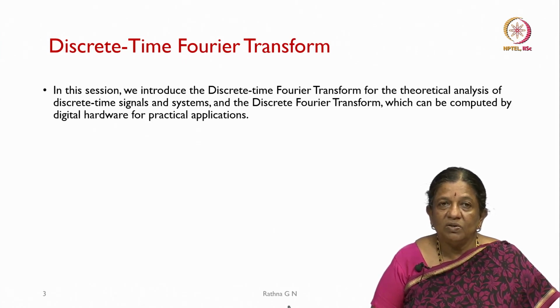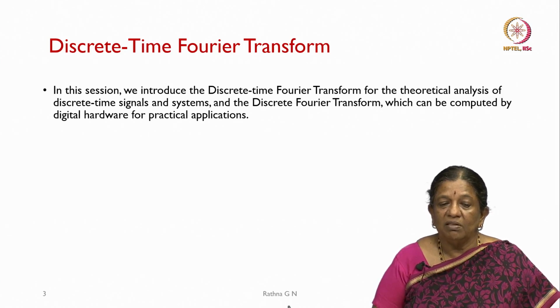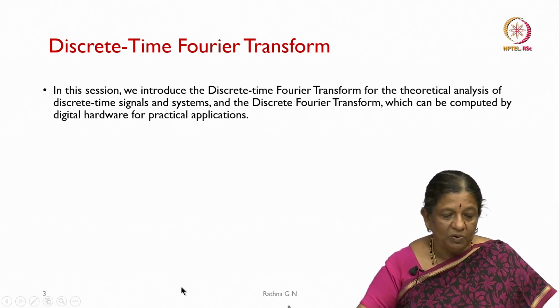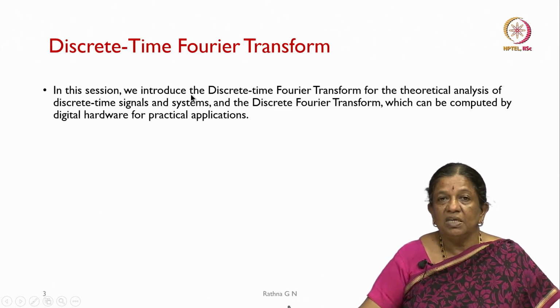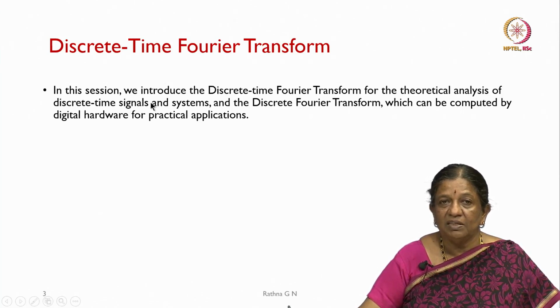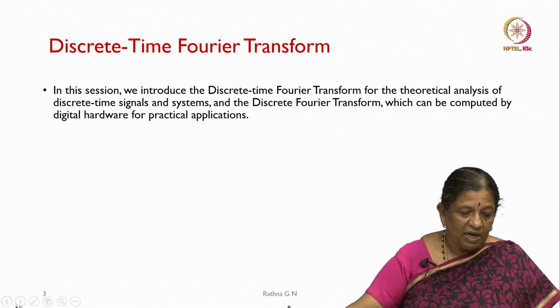Today we will be discussing the discrete time Fourier transform first, and then we will see how the discrete Fourier transform is developed. We introduce the discrete time Fourier transform for the theoretical analysis of our discrete time signals and systems, and the discrete Fourier transform, which can be computed by our digital hardware for practical applications.